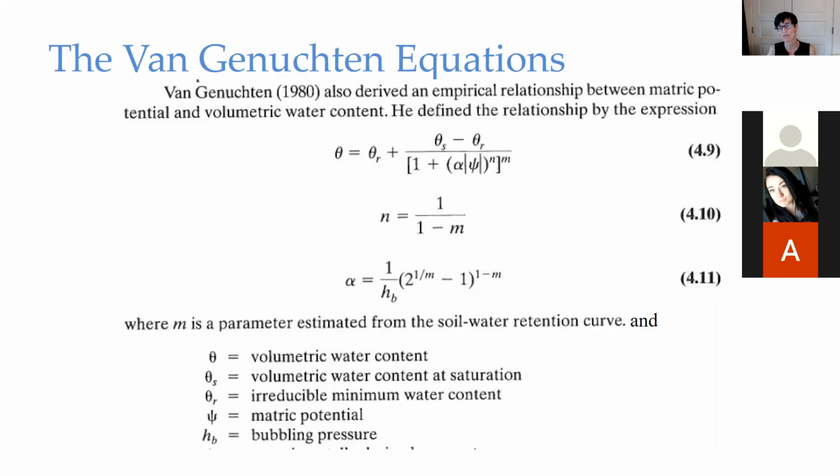And these are the actual famous Van Genuchten equations. This says, what's the moisture content as a function of the pressure? We have a bunch of parameters. We have the saturated volumetric water content if we're determined to work in moisture content. Here's the irreducible one. And then these guys are just our parameters. This alpha, N, and M are all just empirical parameters that you mess around with until you can describe your soil properly.